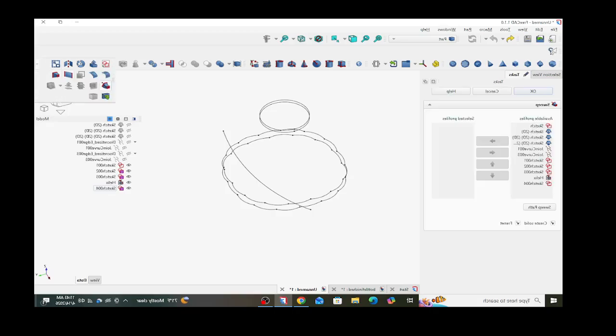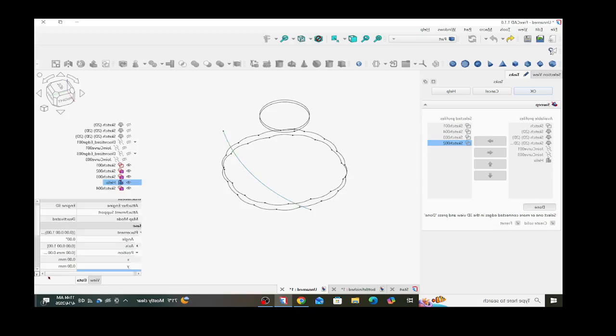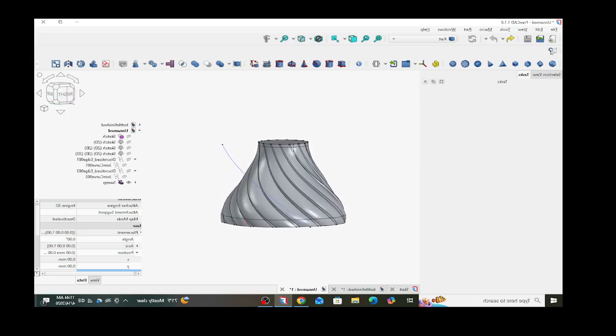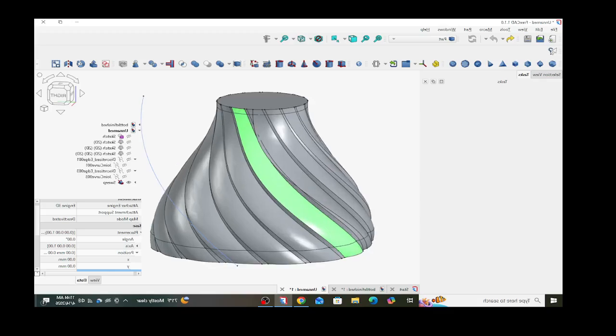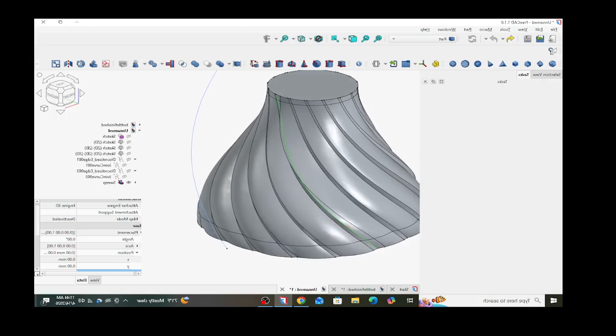Again, we're going in order: sketch 001, sketch 004, sketch 003, and sketch 002. Click on our sweep path and click the helix. Click Done. We want to create a solid, and we want Frenet to be selected. Now that is pretty good. It's not quite what we're going for here. See if we can fix it in a minute.